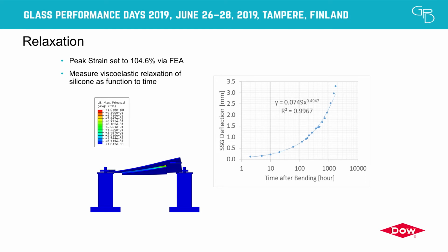And then what we're going to do is not only measure the deformation immediately after that in the sealant after we put the stress on it, but we're going to measure what happens to the sealant as that bent plate is trying to pull it away from itself and go back to its origin, to try to understand if there's a function for creep or rupture.